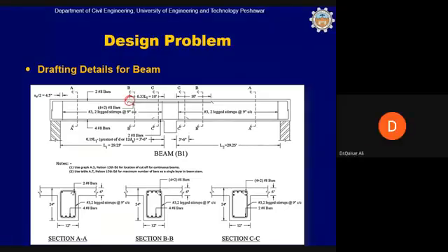Okay. So this small cut tells us that something has been done to the bars in the first layer. Some bars have been curtailed or cut beyond this point. The second layer is very clear. The bars in the second layer do not continue beyond this point. But in the first layer, there are 4 bars.